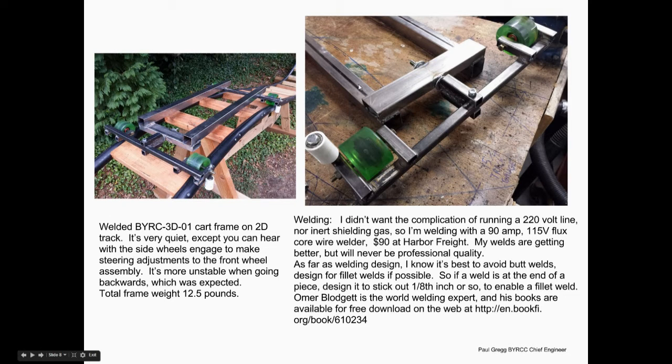I did have to give up some vertical space there maybe, but you can see here I stick them out in front of the cross member there so that I can get fillet welds under them. So fillet welds are much better than butt welds, and try to maximize the length of weld that's holding pieces together. And I think it comes out much better design. The stresses are lower in the welds. It's going to last longer.